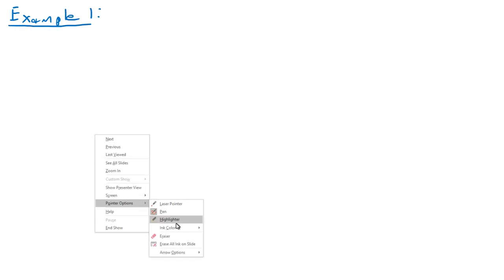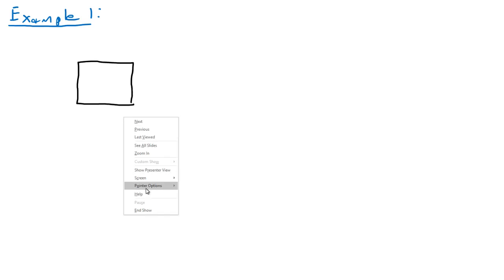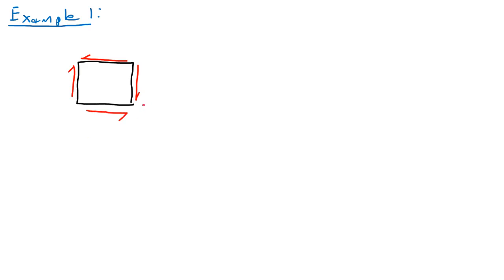Let us say we have a stress block in the following condition. So this stress block is given, we have this state of stress. All of these are given. Notice the way shear stress is drawn, it is negative. So tau xy is, I'm just listing this as 500 psi for now.